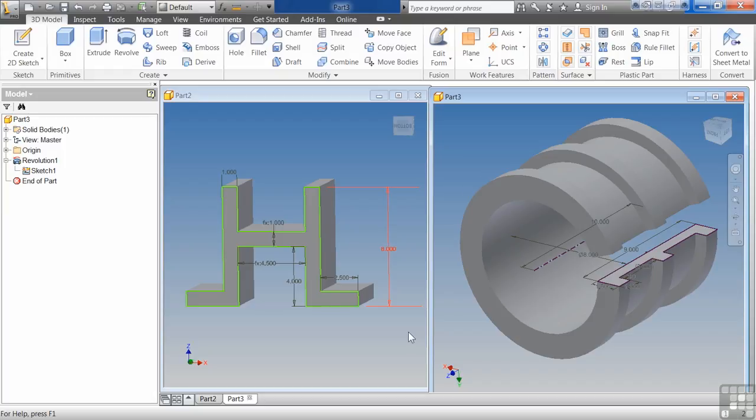What this is telling us is if you're familiar with the old 2D style of drafting, you created a 3 view, sometimes you'd create a section view. And usually this is kind of your front view or your section view of your part, and then it's just revolved or extruded. So it's very simple. Going back to the basics of drafting is thinking about what is this part going to look like in section and then drawing it out. This may not be the completed part, but this is going to be essentially the starting point.